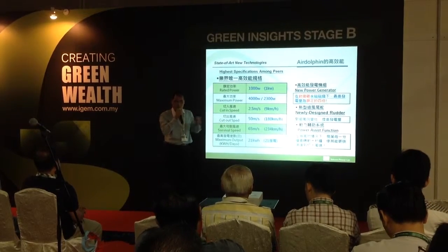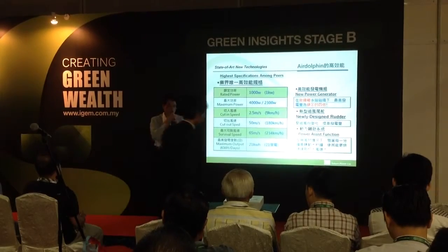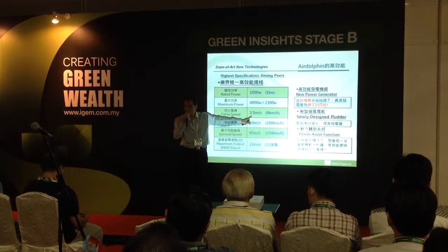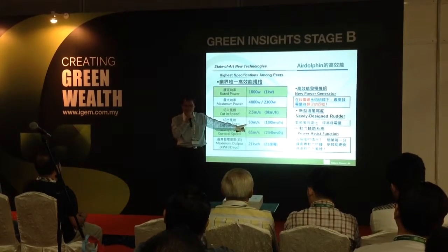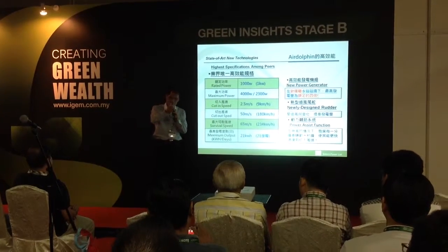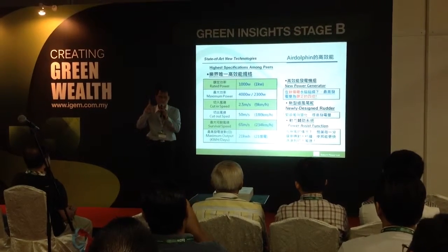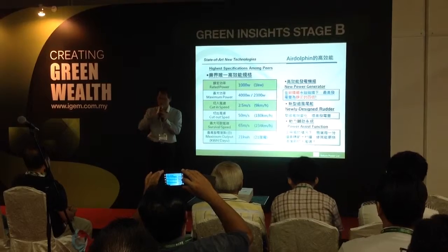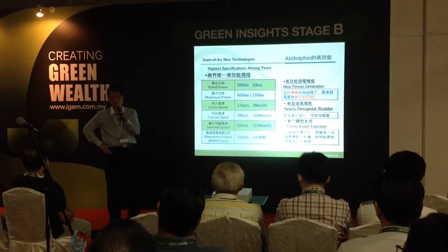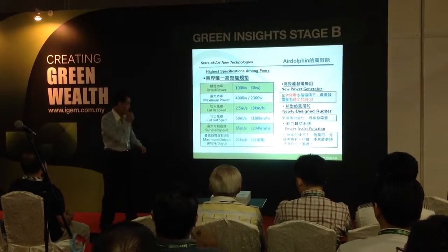These two figures give a good definition of the performance of a good wind turbine, because this wind speed is when it starts to generate power, and this wind speed defines when it stops generating power. So from start of generation to stop of generation, these two figures define a good wind turbine. No matter if you go to the market and the sales say how good their wind turbine is, blah, blah, blah, don't be cheated. Just ask these questions. Okay?